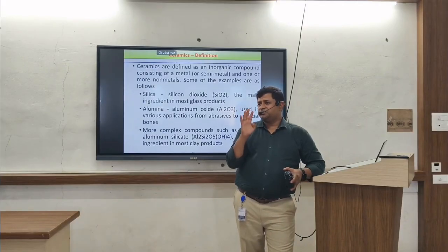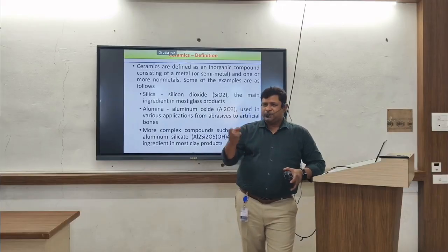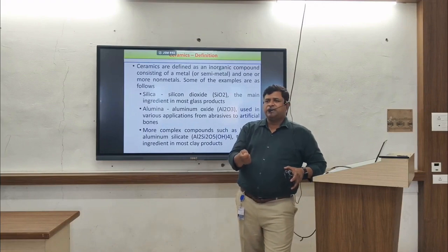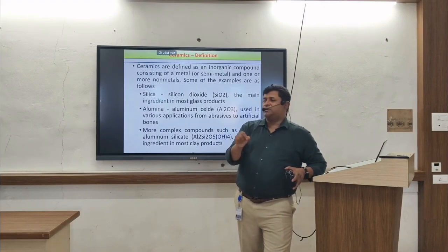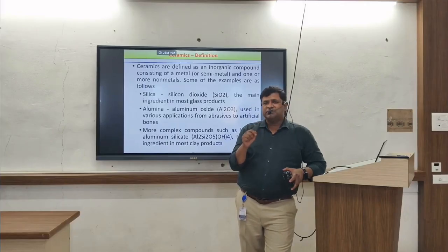For the fine polishing of the steel material, the powder is in the form of paste. The disc is rotating, the sample is there, you just put some water on that, put the alumina particles on that particular disc and polish the material. Your fine polishing will be done.